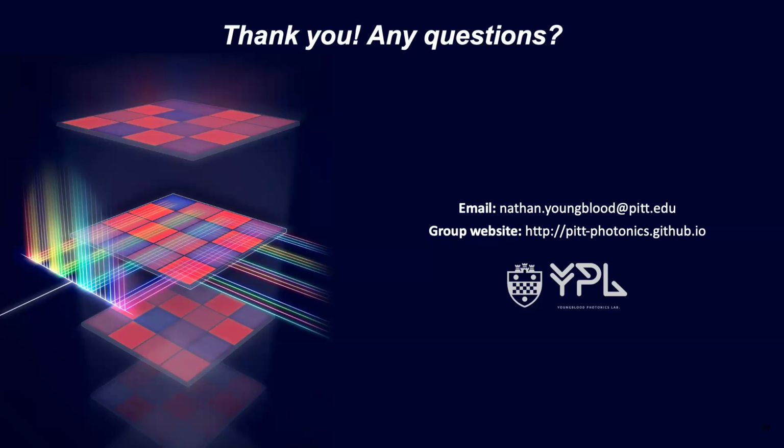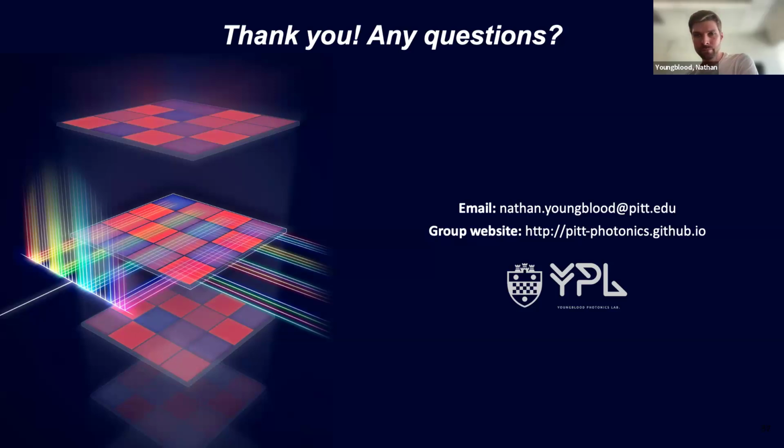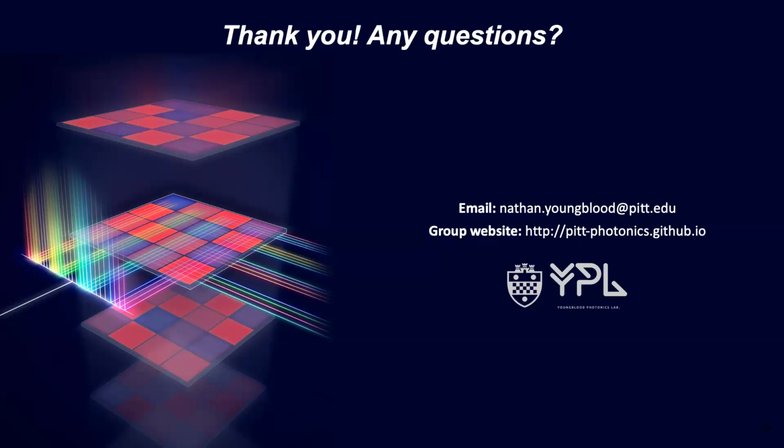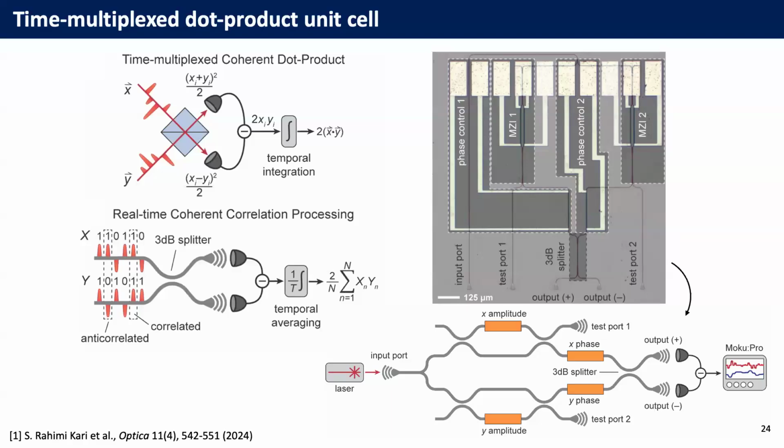I had one question regarding the coherent systems for optical computing. I have seen that if you have long fibers in the benchtop components in the setup, they sometimes cause phase fluctuations. So how do you control the phases of the inputs going into these arrays in the measurement setup? I guess it also depends on the time scale. If you have a time scale less than a microsecond or so, it might be okay, but higher than that, I think we see phase fluctuations. How do you handle that in the measurements?